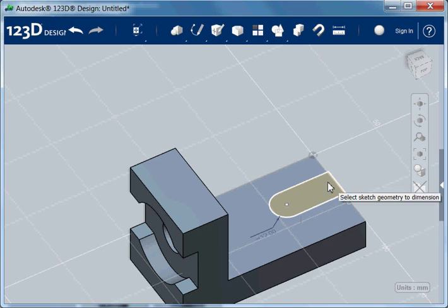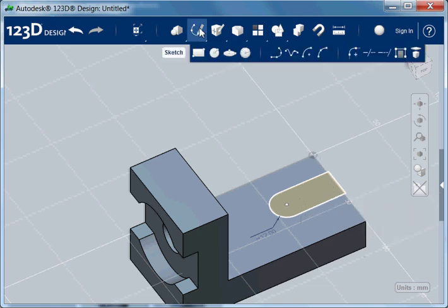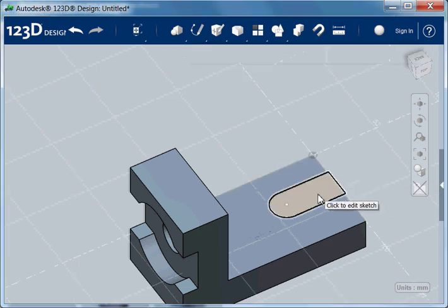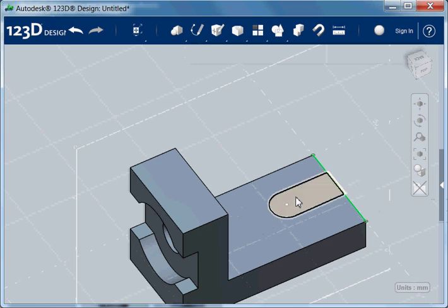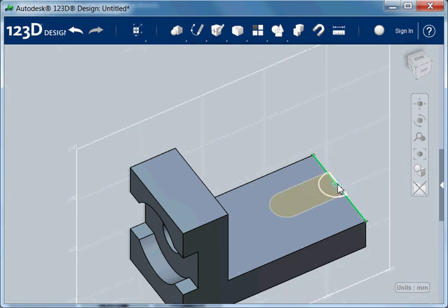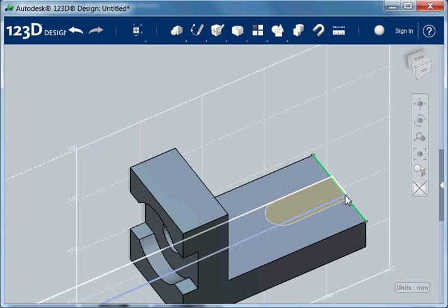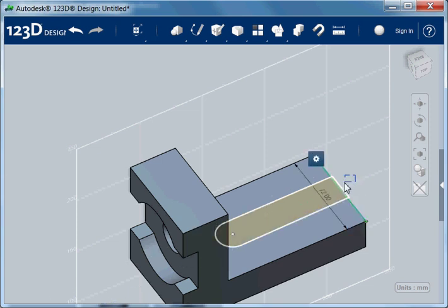I have to include at least this line, so I am going to project. I select the sketch first, and then I select the line. Then I press enter, and if it makes a little triangle, then you know that you're in the center. So if you move there, it draws a green dashed line, which means that it's where we want to have it. And the same thing we do by grabbing this line. I'm trying to grab this line.